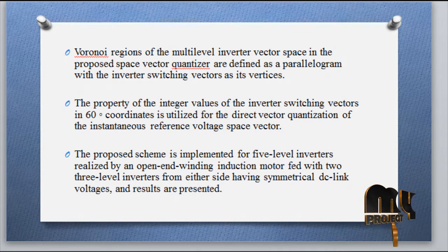And the multi-level inverter vector space is proposed. The quantizer is a defined parallelogram with the inverter switching vectors. These properties of integers and switching vectors give the 60 degree coordinate of the instantaneous voltage space vector. So the proposed scheme is implemented for 5 level inverters realized with an open end winding induction motor.